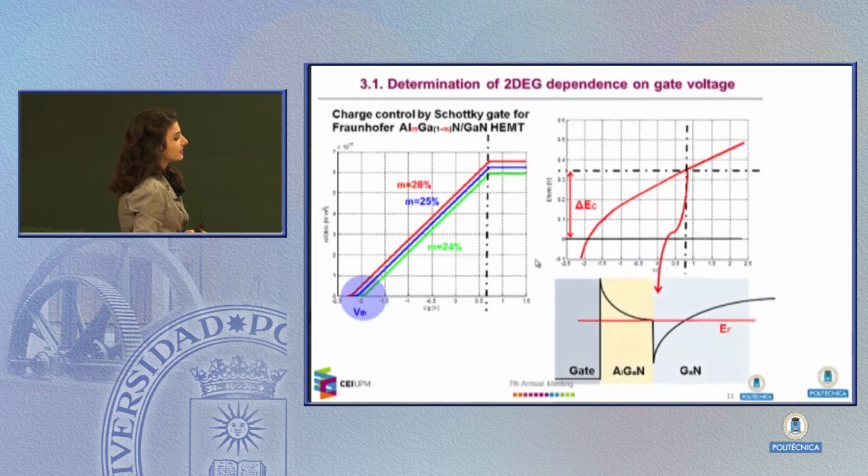And this means that not only will these electrons here saturate, but electrons in the aluminum gallium nitride will also be capable of contributing to the conduction. So this means that we have parasitic conduction through the AlGaN layer and saturation of the 2D gas. So this is the story about the 2D gas model, which is necessary to move on.